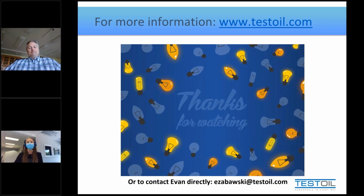Very true. And then we will take this one as our last question. We have a multi-stage equipment, a compressor to gearbox or motor, driven by the same lubrication reservoir. Do you recommend that we take samples from all 3 pieces of equipment? That would be considered secondary sample locations. Most people have a primary one that is just one bulk location for all 3. And until they see a variation in that particular sample point, they wouldn't go back and sample all 3.